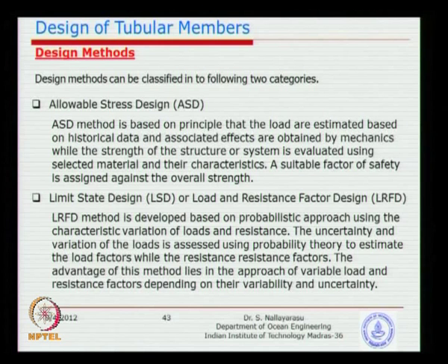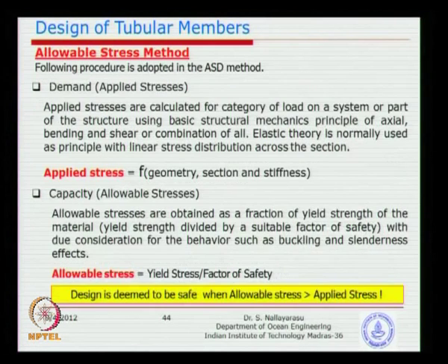So, that is exactly the difference between so-called allowable stress design and the limit state or LRFD. We will just quickly look at some of the factors used in the allowable stress method. Basically, in allowable stress design, the applied stresses are calculated on the system, or an individual part of the system, using simple mechanics principles for axial loading, bending moment, shear, and other components of loading if you have. And basically, elastic theory is used.